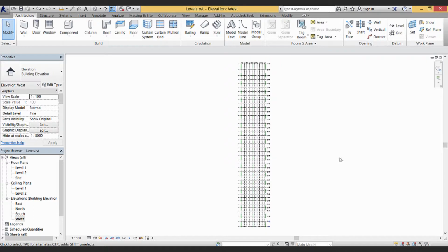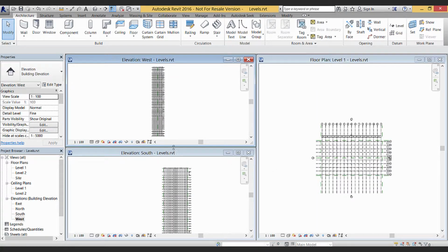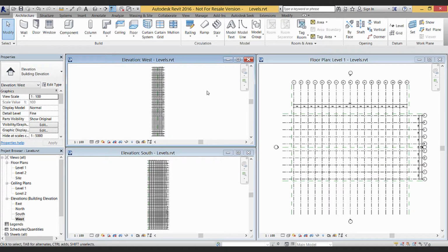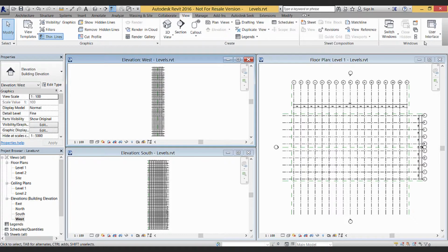Like so. I use, again, ZX on my keyboard to zoom extends this window. So if I use WT window tile, I can now use also ZA like zoom A. I'm going to repeat these shortcuts that are pretty important when you're modeling inside Revit. You use this ZX keyboard combination to zoom extends one window, ZA for multiple windows, and then window tile is the WT. You can actually see these shortcuts, I think, if you go to the view. Let's see here, window tile, yeah, that's WT.